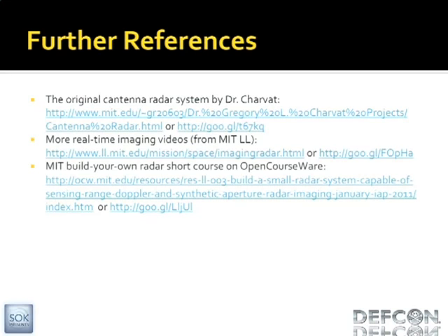Okay, yeah. To some extent, for the SAR stuff, we want something a little less directional than that. Part of it is that the coffee cans were what was available at the time. So MIT students drink more coffee? Well, that's probably true. We could graph that. But yeah, it's pretty open. You basically get different characteristics. If you're trying to do the SAR imaging, having a wide beam width is actually somewhat useful because it decreases some of your spatial fidelity, but you also get a wider image. If you have a very narrow beam, you're not going to get any signal from something that's further apart. So it's a trade-off there.